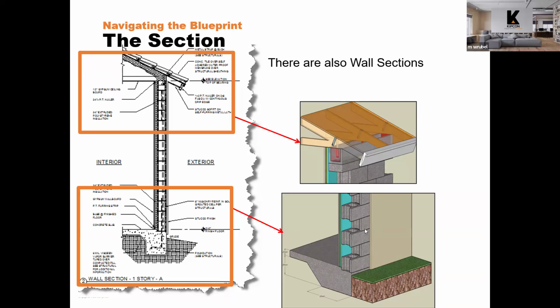And the same with the foundation. You see where that concrete masonry unit wall, the interior, comes down and sits on a lip on the foundation. You can see that here in the wall section, how the CMU, concrete masonry units, comes down and sits in the little notch. It also shows how the exterior siding should overlap the end of the foundation. You see that here, where this exterior facade, in this case stucco, comes down just a little past, usually about an inch past the exterior wall construction, overlapping the foundation.